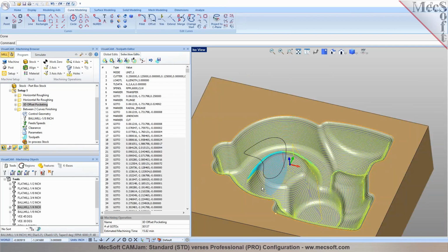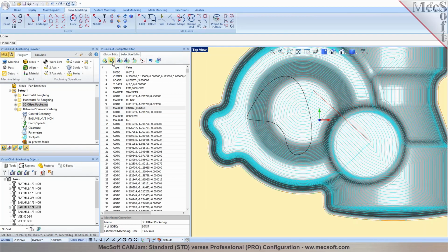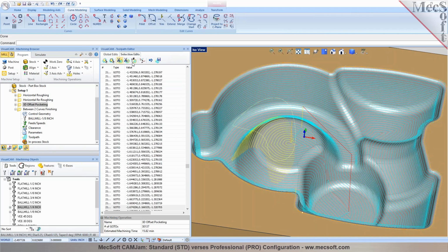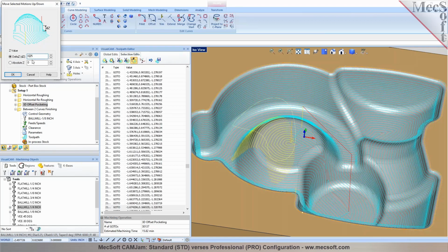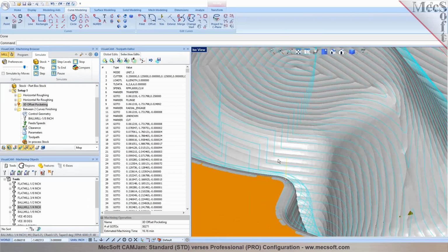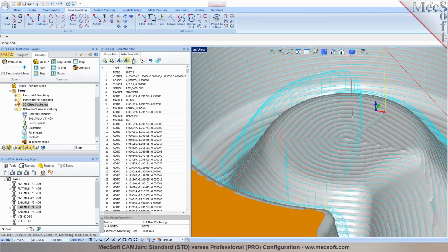And now we can apply an operation to it, whatever type of operation you would like to perform on it. So for example, I can go in and say select the cuts, pick the curve, and then right click. So you can see the toolpaths inside that curve that you created are selected now. I can also isolate it, or I can move it up in the Z. I can say move it up in the Z by 1/4 of an inch, and those toolpaths have been transformed up in the Z by 1/4 of an inch. So you have selection edits. You can select certain toolpaths. You can either cut, delete them, isolate them, or move selections up in the Z,